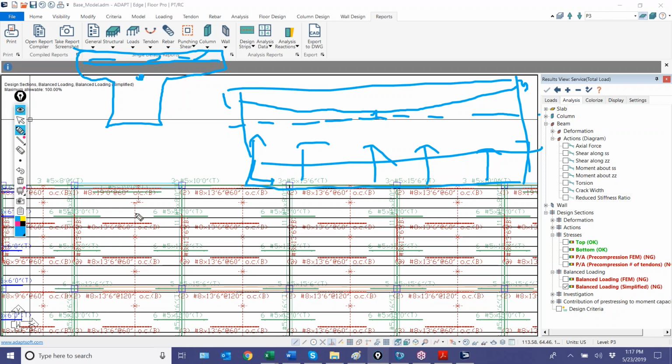But to answer your question directly, as long as the endpoints are not lower than this midpoint, I think it's acceptable, and you also have to maintain proper covers and so on, for the PT. But yeah, this is a little bit abnormal only because these beams are just simply too deep for this particular member. It's just an oversized beam.